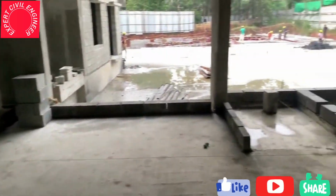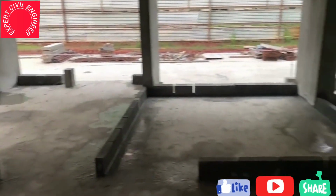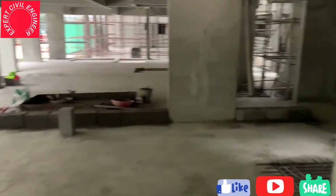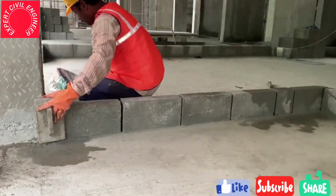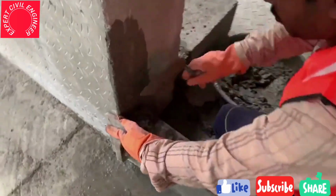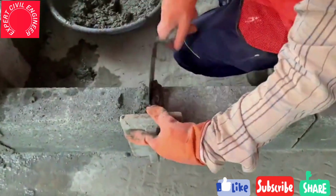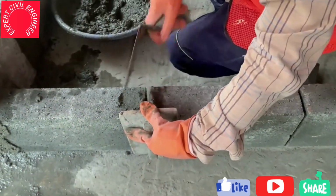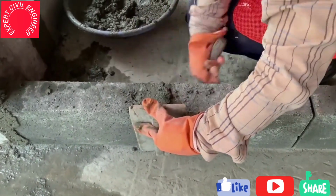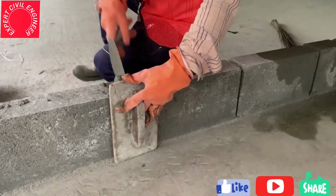Once the preliminary inspection is successfully completed after the marker course, the next step is to prepare for mortar packing. The marking course is considered ready for mortar packing, signifying that the initial inspection has confirmed the satisfactory placement and alignment of the blocks, allowing for the subsequent application of mortar. Mortar packing is the next crucial step after completing the preliminary inspection of the marking course. It is essential to ensure that the mortar is mixed thoroughly and prepared according to the specified guidelines. During mortar packing, keen attention should be given to achieving a precise application without any gaps in the blockwork joints.